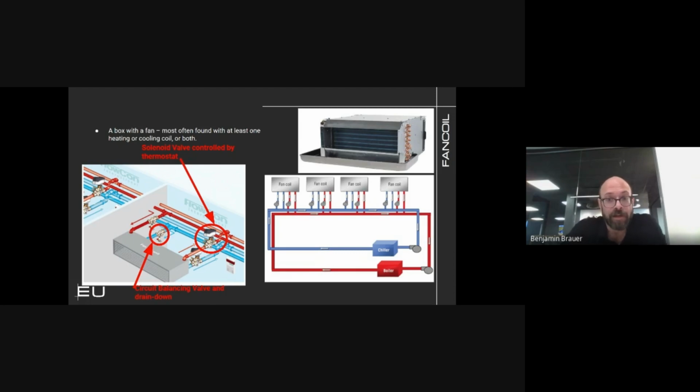fan coils. I'm going to complicate that a little bit. Some of you may have heard of a technology called six-way valves, which is coming out or has been out for a few years now. Six-way valves are a very cost-effective solution to utilize a two-pipe fan coil for both heating and cooling. I'm not going to go into too much detail on six-way valves here, but for those that want to know more, please come by my desk or shoot me an email. I can describe better how six-way fan coil assemblies work. And for those that want to impress our clients, six-way valve assemblies are often a very good VE solution that impresses our clients, should the engineer still be designing with four-pipe fan coils.